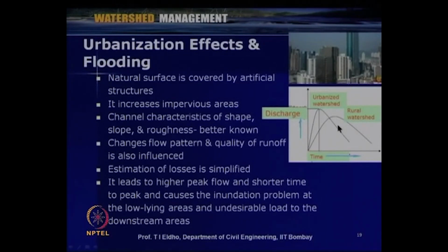So, that way we can see what happens when the time of concentration is reduced. The time to peak is less, and then a huge quantity of water will be coming to the drainage systems or to the streams or to the river, and that will raise the water level, the water depth, and finally flooding will be the effect.